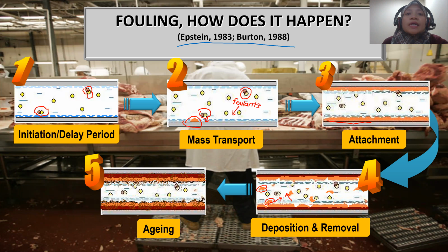This process starts once the material is deposited on the equipment surface. During this period, the adhesion of material can be strong or weak depending on the product materials involved. The deposit may become hard if the equipment surface is hot, and the hot surface will further cook the fouling layer.